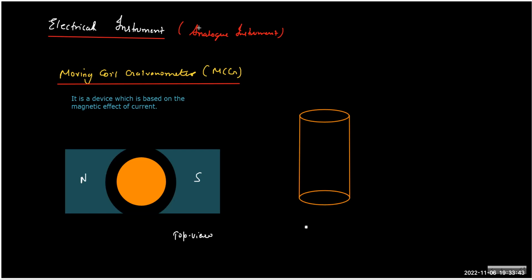So it is the iron core. At the center of the iron core, we have a clamp with a groove. What you will see here is a clamp with a groove, and in the groove we wrap a large number of turns of copper wire. So basically, it's a groove like this. You clamp over the armature, or this iron core, and then you take a thin wire of copper and you wrap it. Just wrap around it.